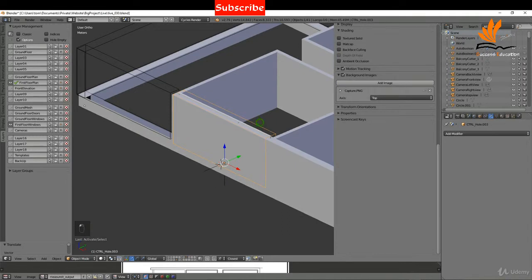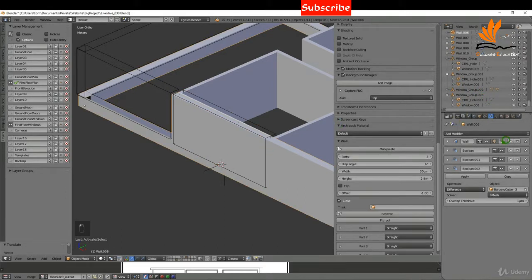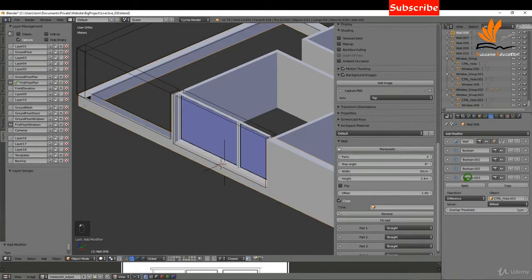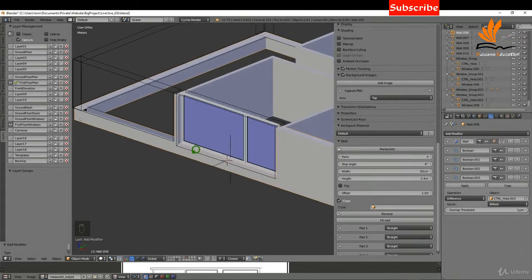So I'm going to select the cutter and just come up to the outliner and press the period key so we can see what number it's at. It's control hole number 3. So if I select this wall, I can add another boolean. It's going to minimize the ones I don't want. And if I click in here, I can type in CTRL and choose number 3 and set this to difference. Okay, and that sits into my wall there nicely.